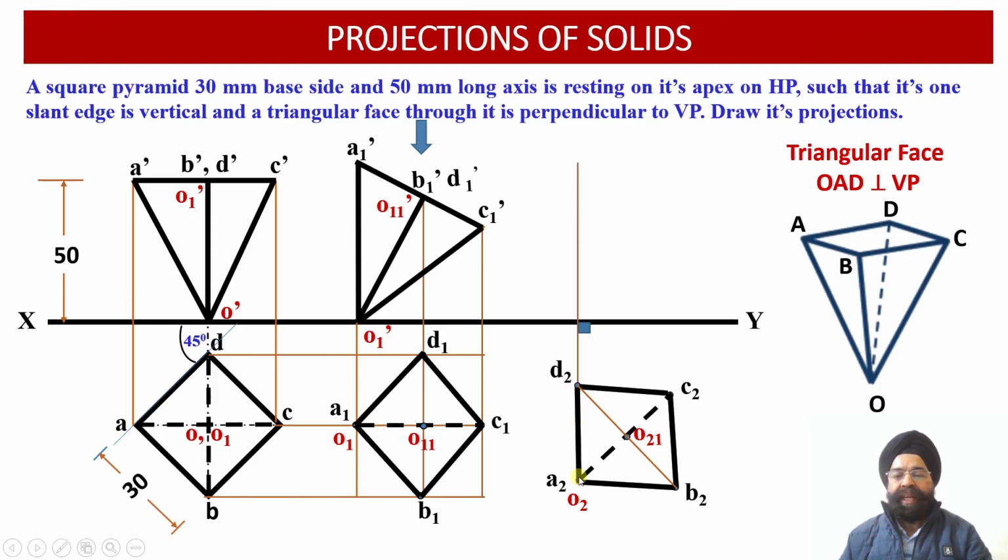Having obtained this transformed plan projection view, we have obtained the plan projection of the oblique inverted square pyramid. The top view projections of this inverted square pyramid have been appropriately obtained onto the horizontal plane. Now again 6 points are available. Finally we are required to obtain these 6 points of the oblique inverted square pyramid onto the elevation projection view.